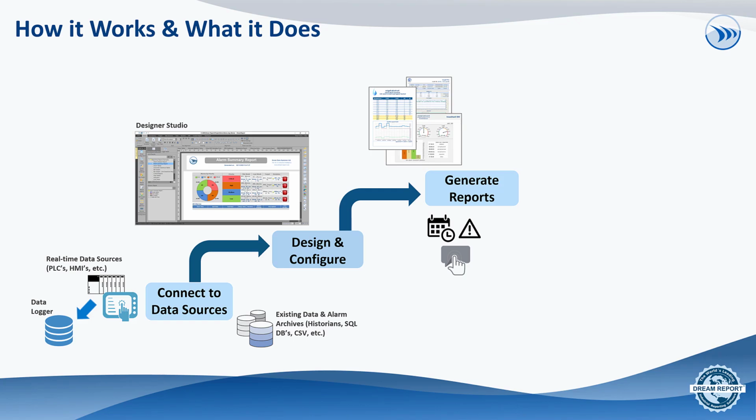For instance, you might have a batch report. A bit goes high in the PLC at the completion of the batch. We want to trigger a report when that bit goes high. We can look at that value. When it equals 1, trigger the report. Or you can even take metrics from one report or calculations in one report to trigger another report. So you're really letting Dream Report look at the data for you and then notify you or send you reporting content when certain conditions are met.